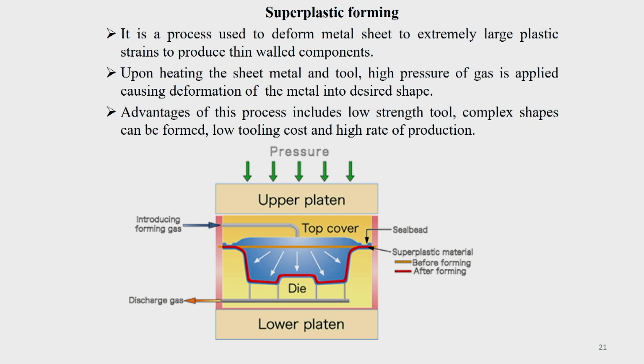Superplastic forming is where, when you are deforming the material, there is no necking taking place. The material exhibits superplasticity when there is no necking. In a tensile test, after reaching the ultimate tensile strength, you will see that the load drops. That is because necking takes place in a localized region, which we mentioned in the first or second lecture of module 1. Under certain specific conditions, most materials will exhibit superplastic deformation.